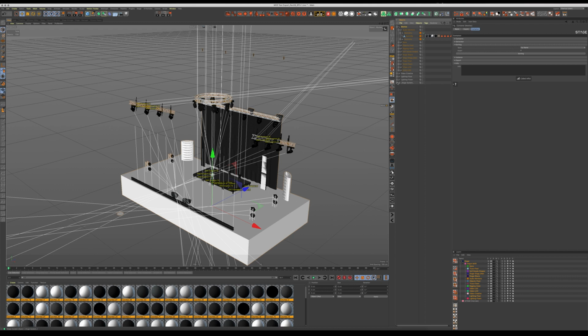So if I look under the stage system, again, let me just sort that. I can see that, for example, here there's some 1 meter truss, various different types of trussing, etc. And these are what are driving some instances. So if I go to my floor truss, here you'll see that I've got some FD34 1 meter, and that is instancing from this item down here.